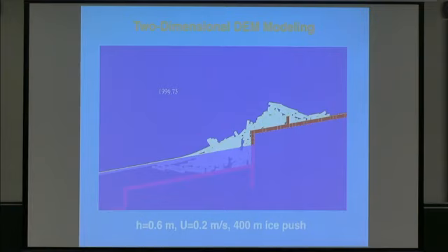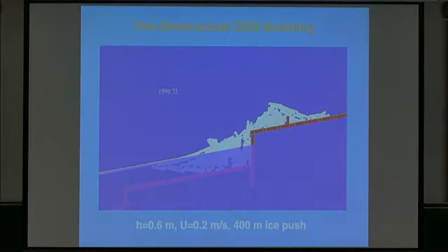So this is the problem with a 2D simulation. Once you've got an obstruction, it's really hard for that sheet to move that obstruction out of the way or climb over it. Whereas in 3D, where you have non-simultaneous failure, you've got the supporting sheet on each side of the obstruction that can help push the sheet that's blocked over the obstruction, you might say. So I just wanted to keep that in mind for later. But it is one of the downsides of the 2D simulation, that when you have an obstruction, that's it.